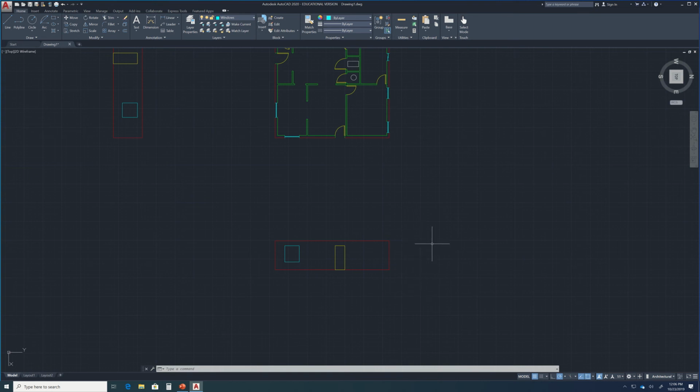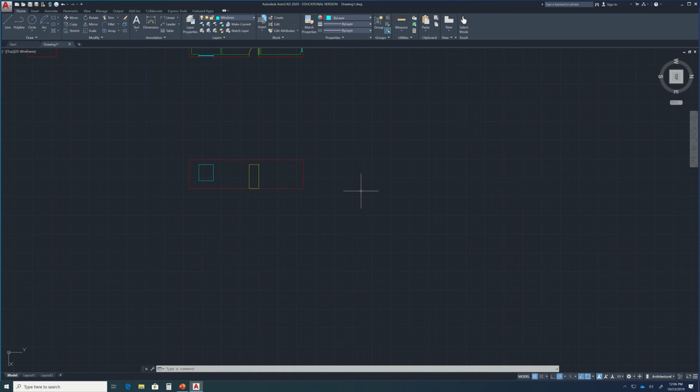So what I want to do now next is I'll also want to indicate my wall height. I don't need to indicate my door height or anything like that because that's just common sense. Okay, but we always, even though the wall height would be common sense as well, we always want to indicate that because there are cases where your wall would be shorter than 8 feet for whatever reasons. So to place the measurement of the wall height out here, well actually I think I'm going to save that for dimensions. That's what I'm going to do. I'm going to save that for dimensions.